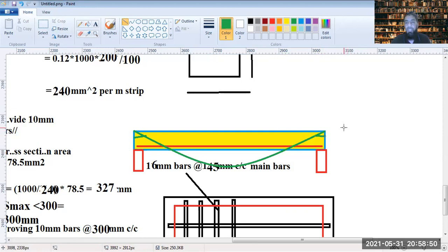So even in the case of simply supported, where the ends are prevented from uplifting, the slope does not come out to be zero at the ends, it comes out to be a value greater than zero towards the end. So there is a certain amount of tensile stresses developing towards the ends, and there could be a case of torsion also developing.